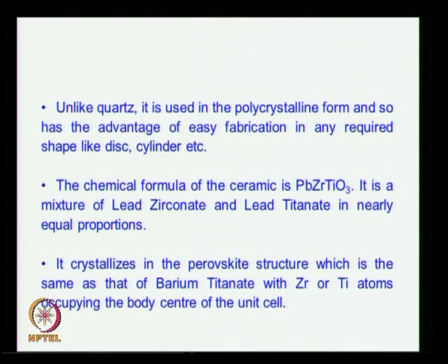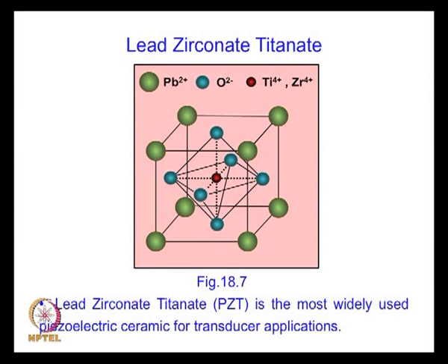So, this is the most widely used piezoelectric ceramic for transducer applications. It is also used in the polycrystalline form, so it has an advantage of easy fabrication. That is the crystal structure of lead zirconate titanate, and this is the most widely used piezoelectric material.